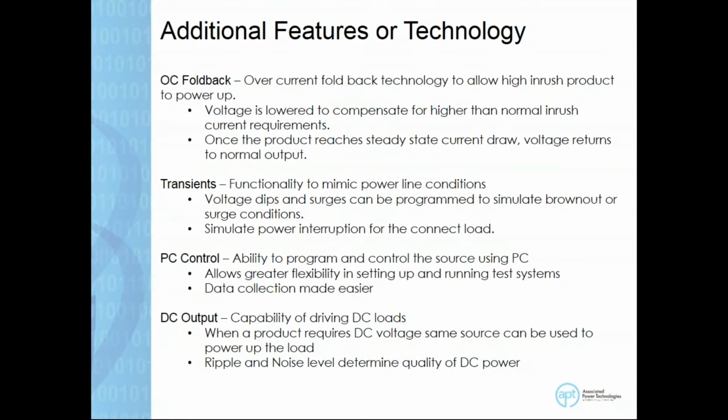When the motors first start spinning, there is a requirement for much more power draw, much more current being drawn, but once the motor is already spinning, it may not require the same amount of current. So this is what we call an inrush period requirement for having a lot more current for the product, and then a steady state area where the motor is already spinning and doesn't require that much current to keep it spinning.